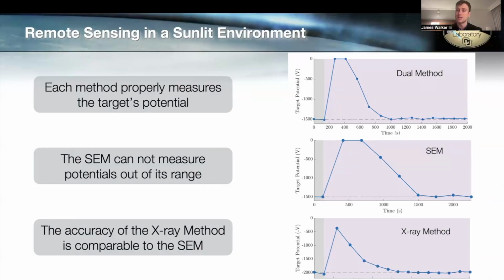Now, in this dynamic environment, because our voltage sweep is only from 0 to 4,000, we're not accurately measuring the target's potential anymore. So even though it appears for this positive bias we are able to get nice control, if we were to have a negative bias, or just in a dynamic environment where the potential jumps outside our initialized voltage sweep bounds, we won't be able to accurately measure or control the target's potential anymore.